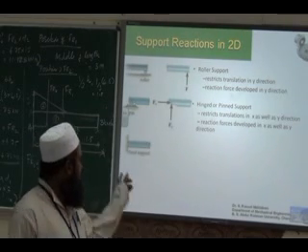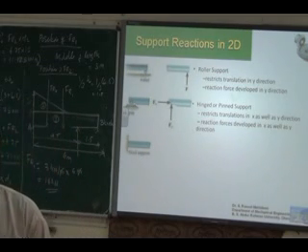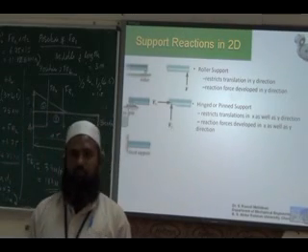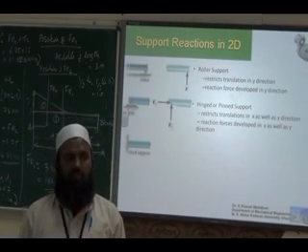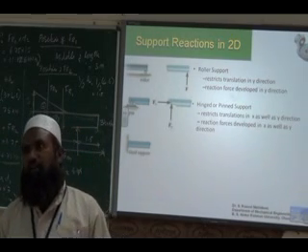Okay, next kind, we have a fixed support. So what type of reaction will we have? What type of restriction do we have? It cannot translate, it cannot rotate. No translation in X and Y direction.